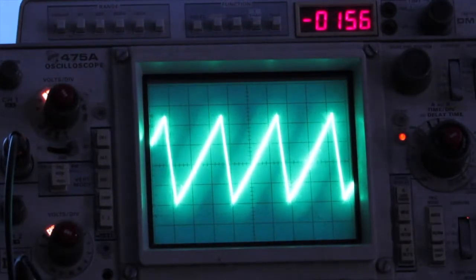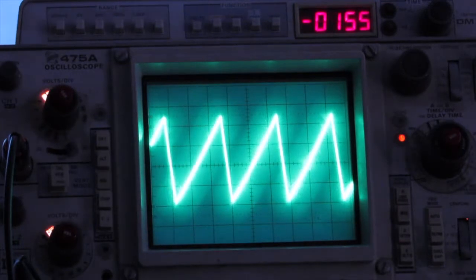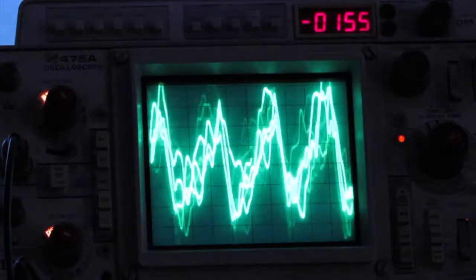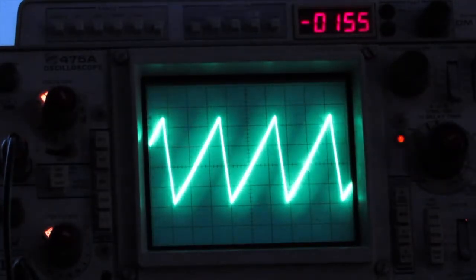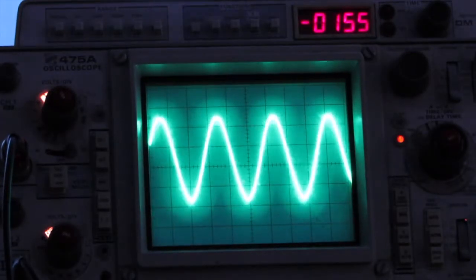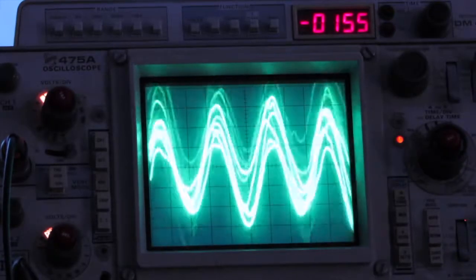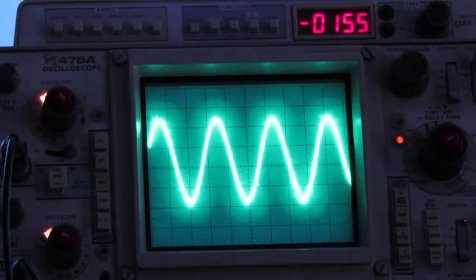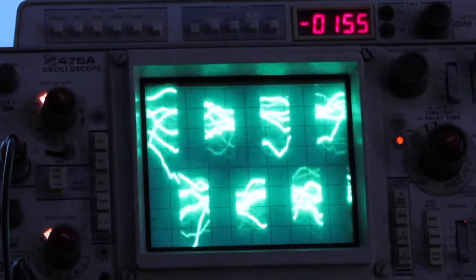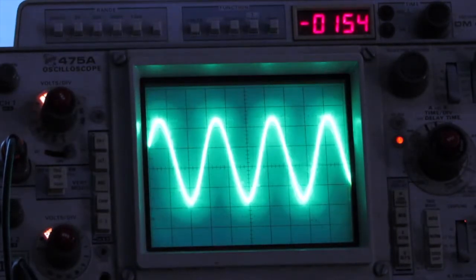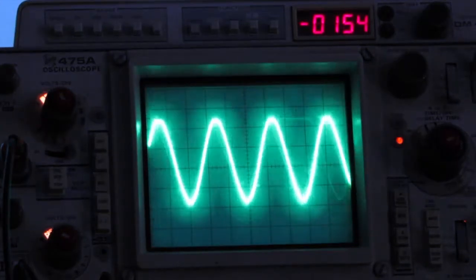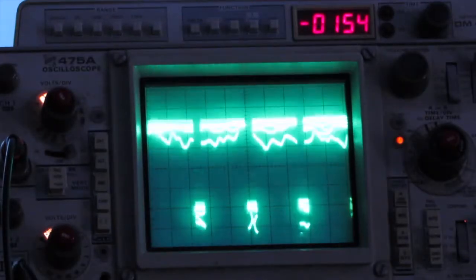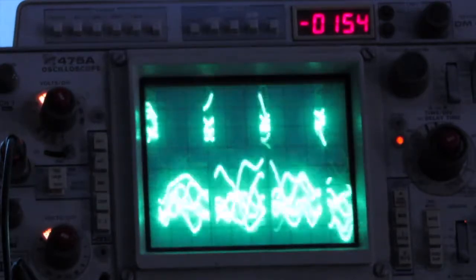This is really good if, let's say, you want to compare two signals. You can invert channel 2 so you can subtract the two channels too. So if you want to compare the quality of two microphones, you can plug both microphones into the scope, invert one and add them, and if you speak into both microphones, it should be a straight line if the microphones are identical, because they're subtracting the audio from each other. But if one has more bass response, you might see a large waveform, things like that. There are many things you can do by adding and subtracting the channels together, which are really advanced things you can do with the scope.